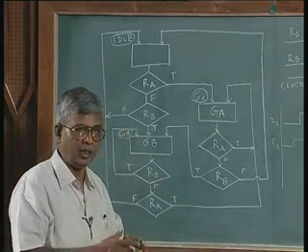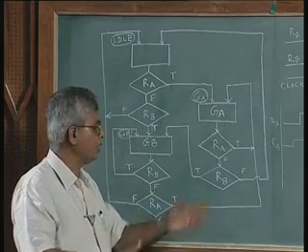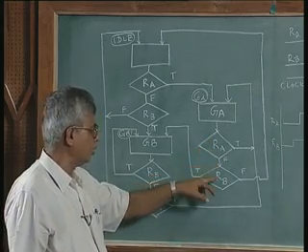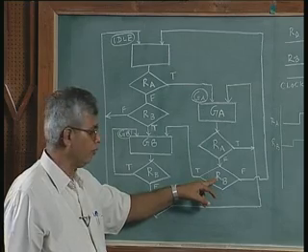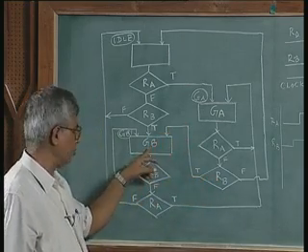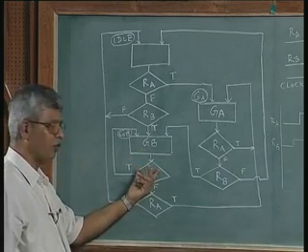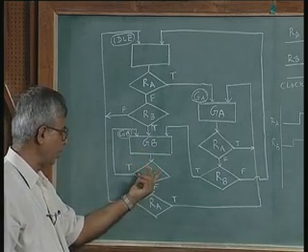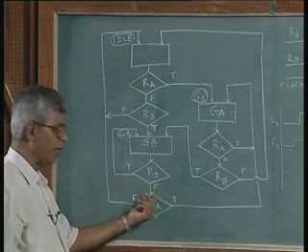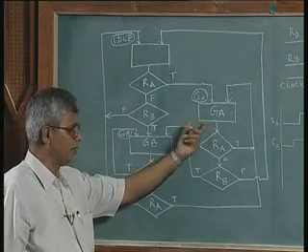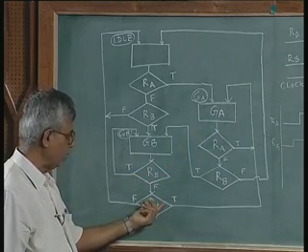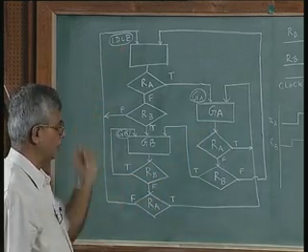That means GA is available for the entire duration for which RA is true. After it is done with that, it checks if B also requires the bus. If yes, it generates the grant B signal and again holds it for as long a period as RB is held high, and when it is done, it goes back and again checks RA in between. RA could have asked for one more request, and that will be tested again. If there is no such request, it goes back to the idle state.